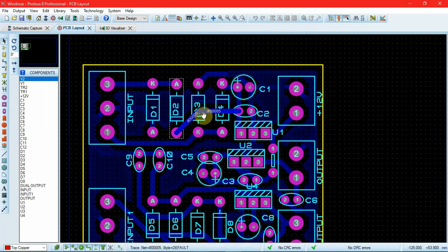In the PCB layout, we can see that just after the bridge, the capacitors are placed so close to each other. Why? Because their role is to reduce the noise that is entering the regulator IC.